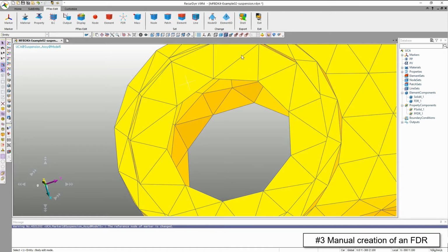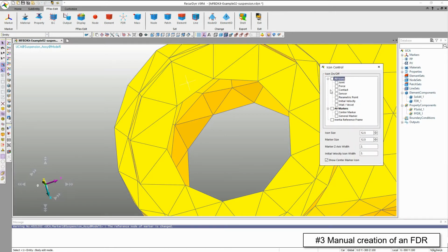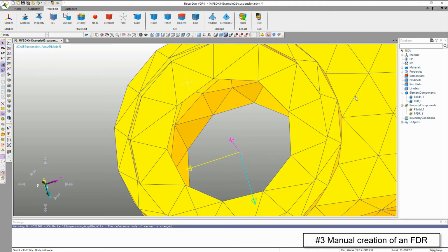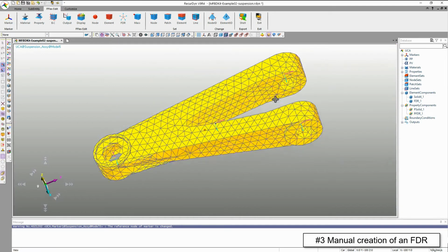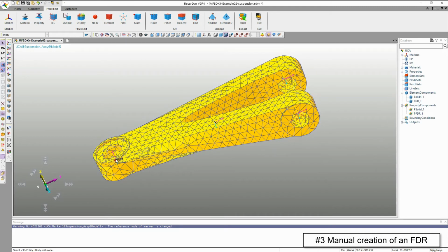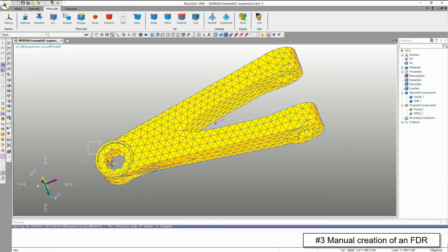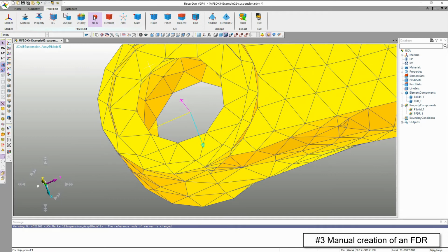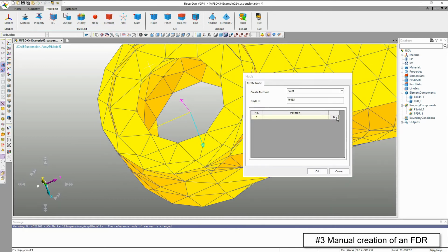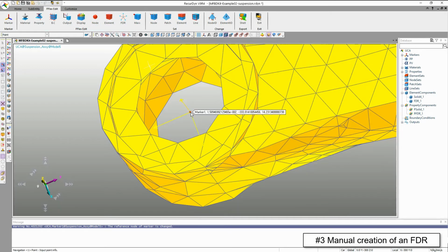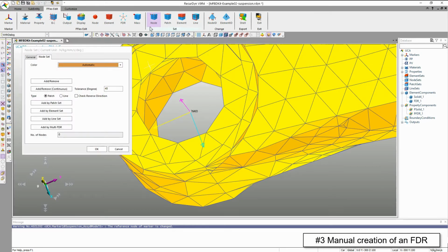First, display the markers. Three markers are the ones connected to the joint and bushing force, respectively. Click the Node button and click N, then select the marker in the middle. Then one node is created where the marker is located. This will be used as a master node.